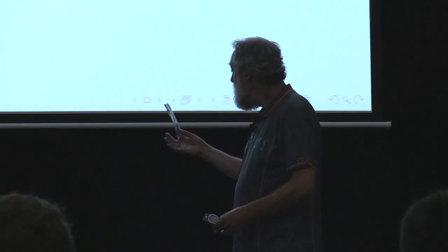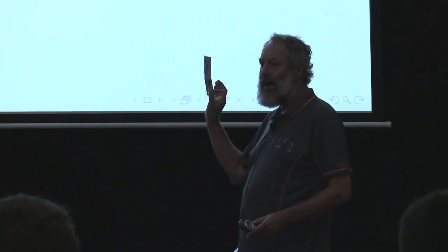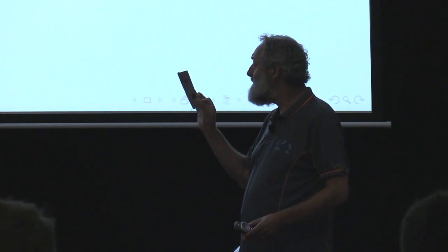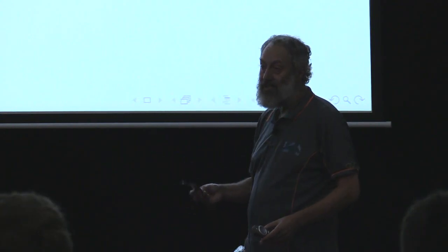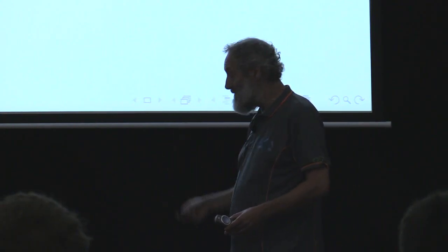So how can we make bigger caps yet? These ones are like a couple of nanofarads at the most. I did try a different book covering plastic, by the way. This one here, which is about the same size as that one, is 1.5 nanofarads at the moment. I haven't had it long enough to find out whether it's going to decrease over time. It's a different book covering plastic. So what we can do is try increasing the area or decreasing the distance between the plates.